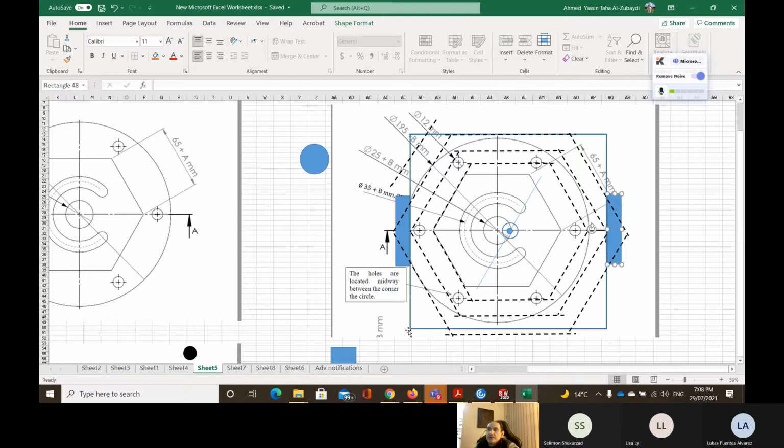So if I'm going to decide that this corner, which is actually going to be like that, because the device is not going to be that small, above this side of the jaw of the device is going to be the datum point, where x is going to be 0, y is going to be 0, and the height is going to be 0. Usually we choose it a little bit above the work part, at the top of the work surface, or the highest point is going to be actually the highest surface we have for the finished part.